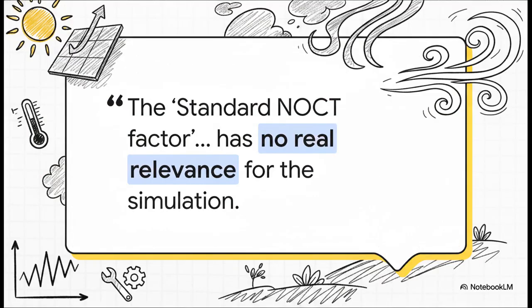Listen, whatever you do, do not just rely on standard manufacturer NOCT ratings for this step. Those tests are run under highly specific, controlled laboratory conditions that your project is frankly never going to experience. By manually inputting the correct heat loss factor for your specific mounting type, you are forcing the simulation to embrace the messy, thermal reality of the outdoors. That is exactly what separates an amateur design from a true, expert-level, bankable simulation.